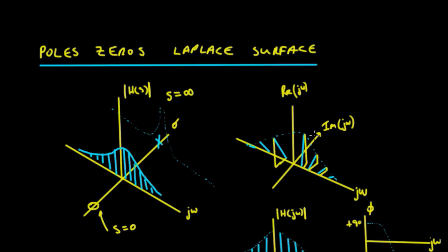If we were to draw it out in this section in 3 dimensions, we would have an imaginary part, a real part, and our j omega axis. But note that we can't actually draw it like this on this graph because we don't have enough axes, because this axis isn't the imaginary axis, it's the sigma axis. But we can take this slice and represent it in a 3-dimensional sense, so it's equivalent to having our phasors rotating round about on the j omega axis here in 3 dimensions.